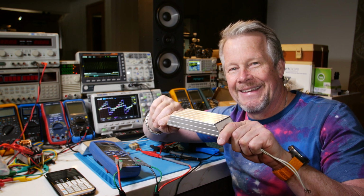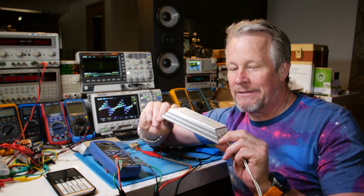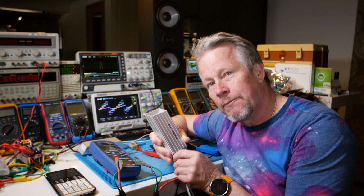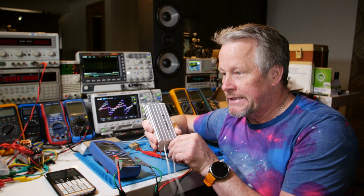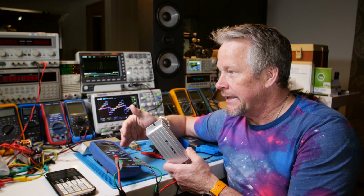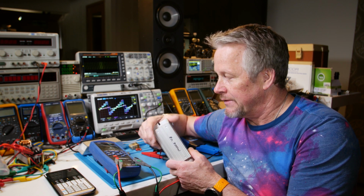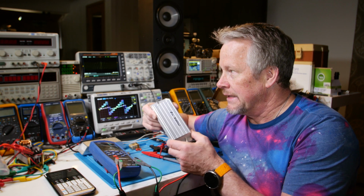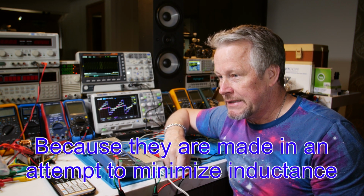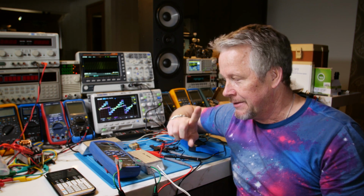Well, imagine we're zoomed in on a small surface mount part, and we have these little pads here. Just the length of those pads adds some inductance. So at some frequencies, the higher the frequency is, the more the parasitics come into play. For audio stuff, 20 hertz to 20 kilohertz, it's surprising, but you still get parasitics even at those frequencies. So that's why we call these non-inductive resistors. I'm going to grab another resistor. I want to show you the difference between two types of resistors.